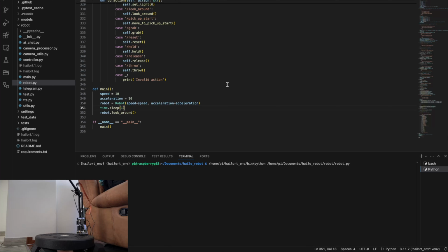You can see the robot is looking around very tentatively, set to speed 10, acceleration 10, which is considered medium settings on this arm. Once this is done, I can crank this up. The interesting thing here is 20 is the top speed, but if you really want to get the max speed out, you set it to 0, which is kind of infinite.